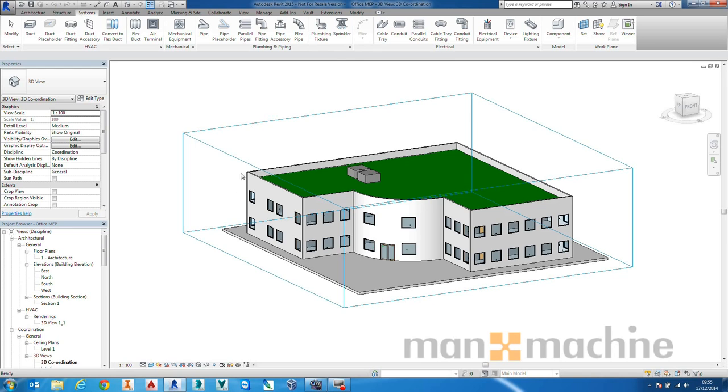In the center of the screen is obviously where we have our model, our 3D model, and when we do the majority of drawing, you'll be glad to hear that inside of Revit MEP we actually do all of our design work in 2D and kind of get the 3D for us automatically, which is great. On the left hand side we have two sections of the user interface. We have our properties. With Revit and with BIM, metadata is all important. So when you select a product or an item or a component, it's going to give you a full breakdown of that component and allow you to view, edit and change metadata as necessary.